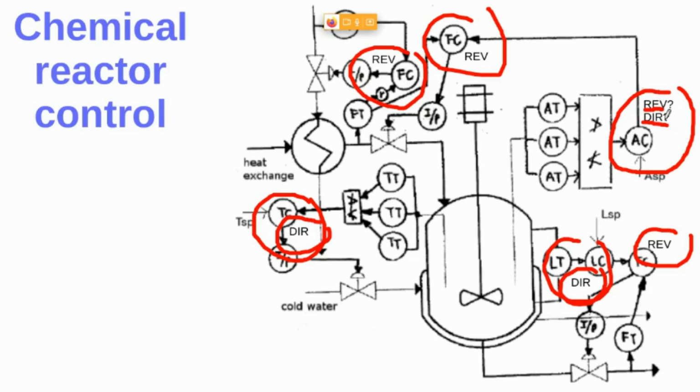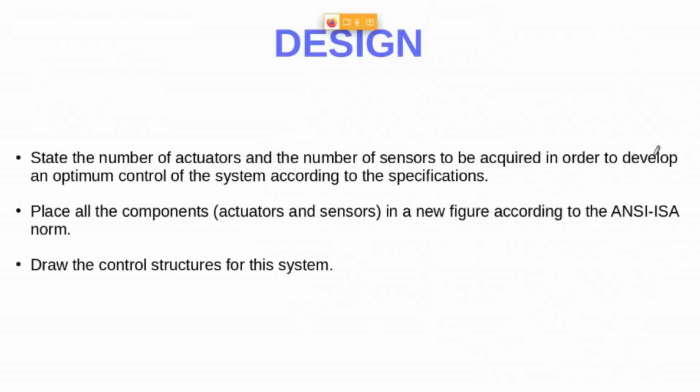So we should ask the chemical engineers or the chemical staff, right, to tell us what will happen with this analysis transmitter value if we increase this variable. If the relationship is positive, then we will use the reverse controller action. If the relationship is negative, we will use the direct controller action.